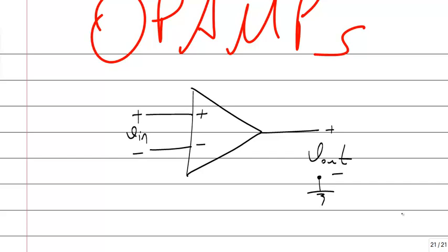And the input voltage is amplified. Where does the high voltage come from? It comes from the voltage sources. Positive voltage source, negative voltage source. Okay? So if you connect plus 15 here, this should be minus 15. If you connect 0 here and 30 volts here, it assumes 15 volt is 0. Okay? The midpoint is ground. It uses the midpoint as the ground.